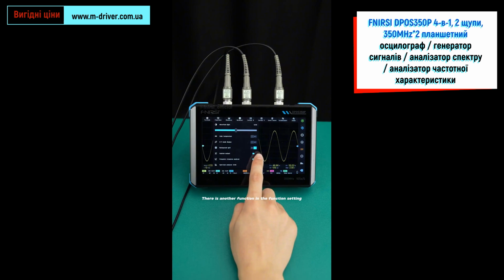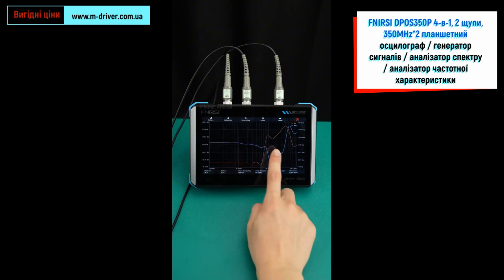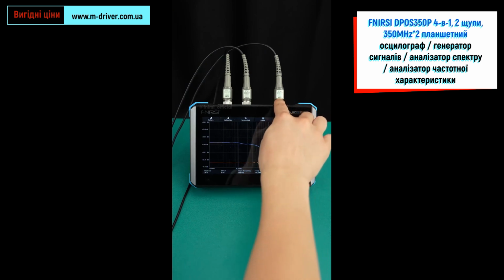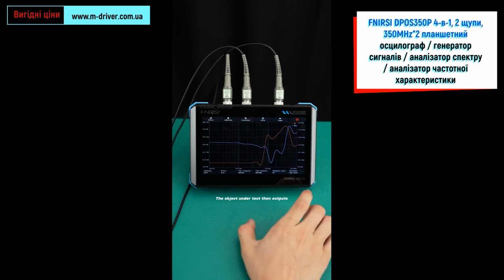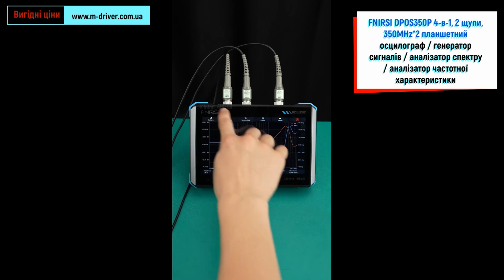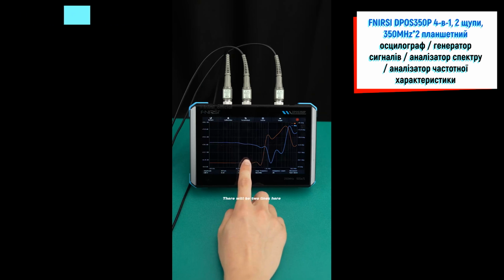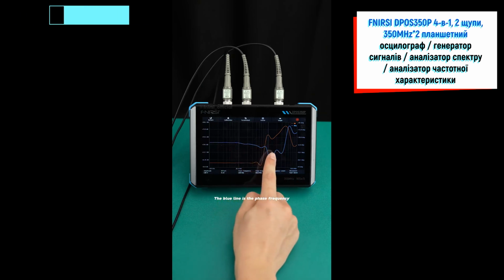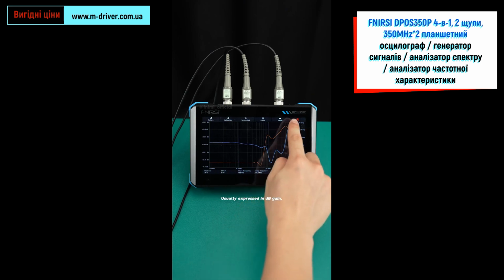There is another function in the function setting, the frequency response meter. Through this output interface, output a signal to the object being measured. The object under test then outputs a signal after the response, back here through the two probes of the oscilloscope. Normally, there will be two lines here. The blue line is the phase frequency, the change in phase with frequency, usually measured in degrees. This yellow line is the amplitude versus frequency, usually expressed in decibel gain.